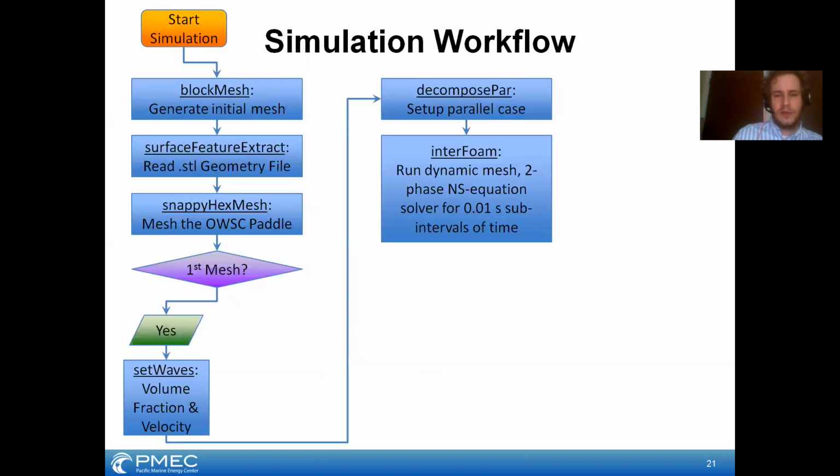And after that, you want to decompose your case and start running it using interFoam. And we ran for sub-intervals of 1/100ths of a second. This is so that every 1/100th of a second, you're going to check the mesh quality and then restart the solver after that if you pass the checks.